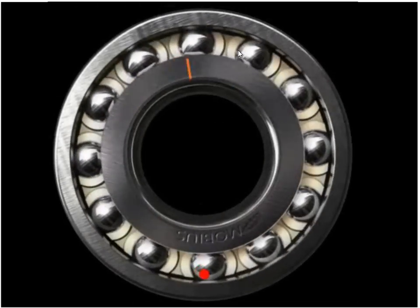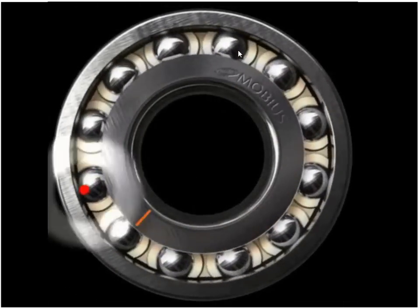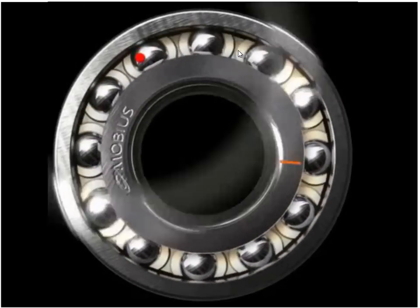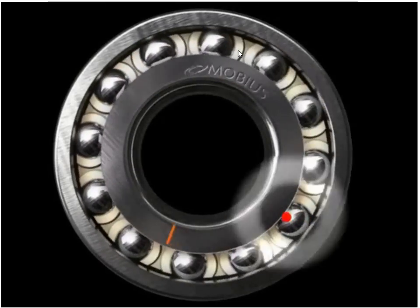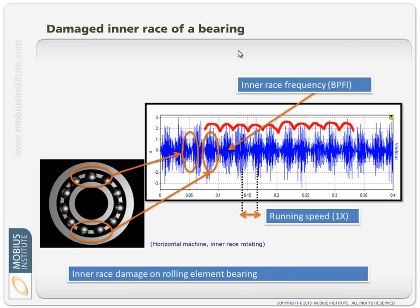Imagine here we have a rolling element that is damaged, and that rolling element rolls up out of the load zone, and now it's going to go down into the load zone. Well, this is what the time waveform shows us. In the load zone is where the amplitude's highest, out of the load zone is where the amplitude's lowest. So that's the load zone, that's taking all the weight of the machine, and there it is here, and that's not taking the weight, so the impacts are weaker.